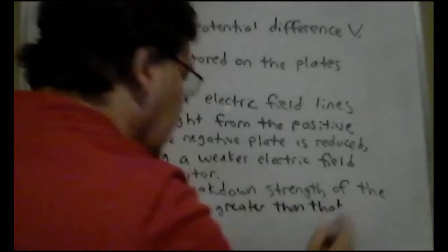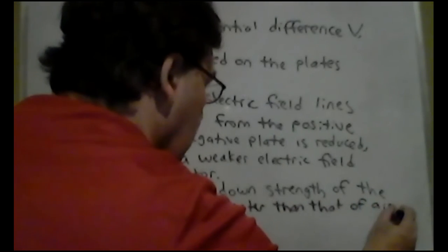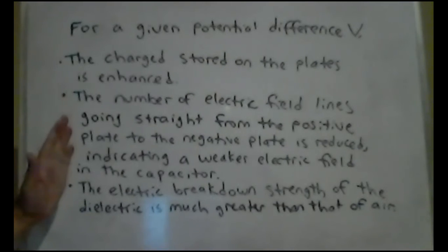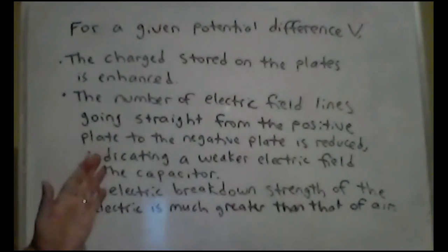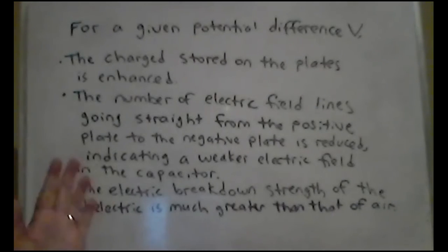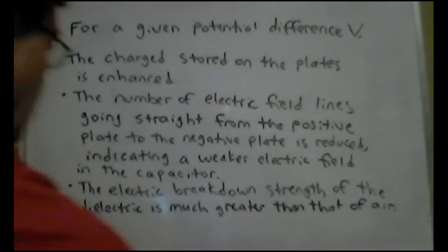It has a much better ability to maintain electric field. So any way you look at this problem, it is a win-win situation. You get more charge for a given voltage. You have a weaker electric field, and not only that, the dielectric has a greater ability to hold an electric field than air does anyway. It has a greater breakdown strength. So everywhere you look at it, it is a win-win situation.